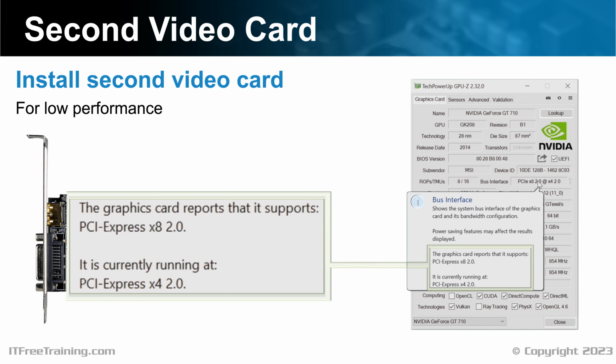You may want to experiment a little bit. For example, if your primary video card is running with 16 lanes and your second video card with 8 lanes, this is fine. If you find both video cards are running with 8 lanes, as your main primary is the primary video card, you may want to move the second video card to a different slot so it uses fewer lanes. If you have spent a lot of money on your video card, you don't want the second cheap video card reducing its performance.